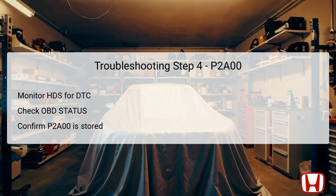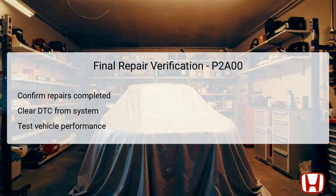Verifying the OBD status and the presence of this specific DTC offers insight into the AF sensor's engagement and the vehicle's overall emission performance. Once the necessary repairs have been performed to address DTC P2A00, it's crucial to confirm that the repairs were effective. Begin by ensuring that all of the repairs outlined earlier in the troubleshooting procedure have been successfully completed. After verifying repairs, the next step involves clearing the DTC from the system using the Honda Diagnostic System, HDS.